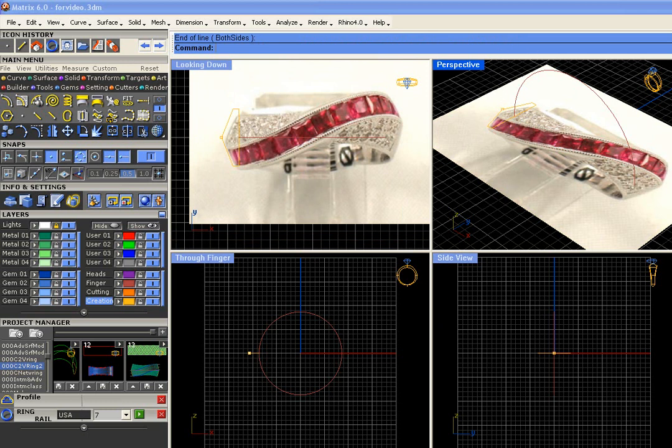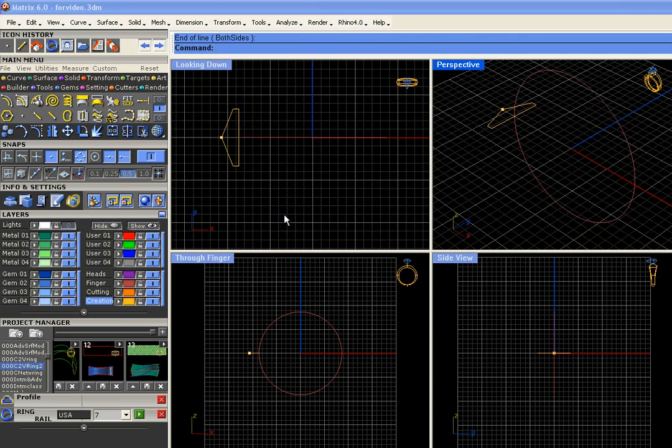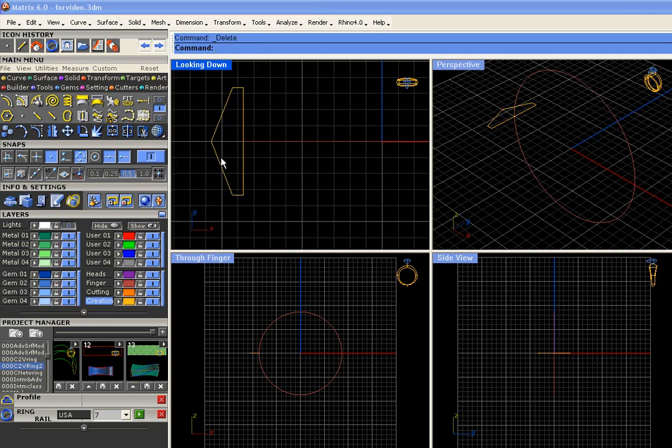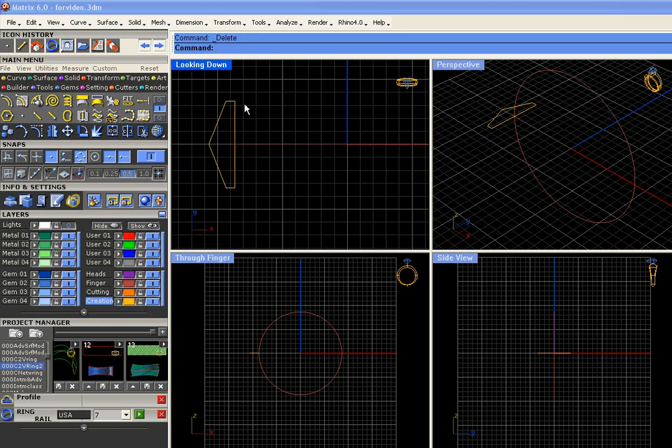Okay. Now if you need to, you can turn off the lights layer. We also don't need this little guy anymore. Okay, the next order of business is to fillet the corners of this profile. Let's use the fillet corners command. Grab the polycurve to fillet, press enter. We'll use 0.2 millimeters. Okay, that won't work unless this is joined. So go ahead and join it up. Now I use fillet curve, 0.2 millimeters, enter.